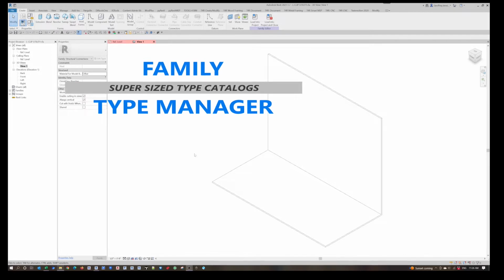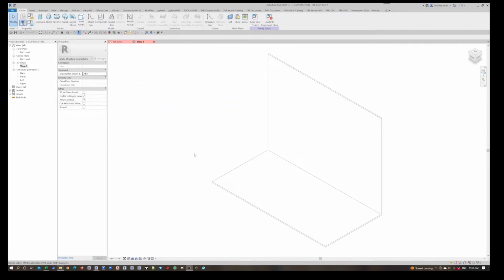In this video, we're going to go through the process of using the Family Type Manager Pro version to create a master catalog of a metal framed clip with all parametric values. We'll build out all the different types for the manufacturer's criteria of clip offerings. We'll also generate and convert that catalog into a master catalog with multiple language type configurations, and also in Imperial and in metric.